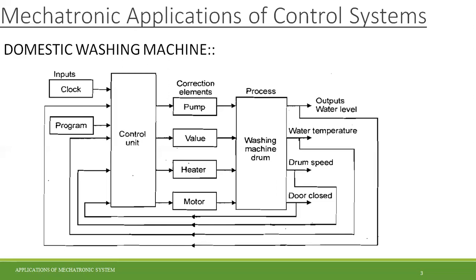For heat conditions, it is a hot water washing process. Also, a heater is required, so the heater will be switched on for a nominal amount of time that we have given in the input program, or a temperature sensor will be placed in the washing drum until the particular temperature given by the instructor.